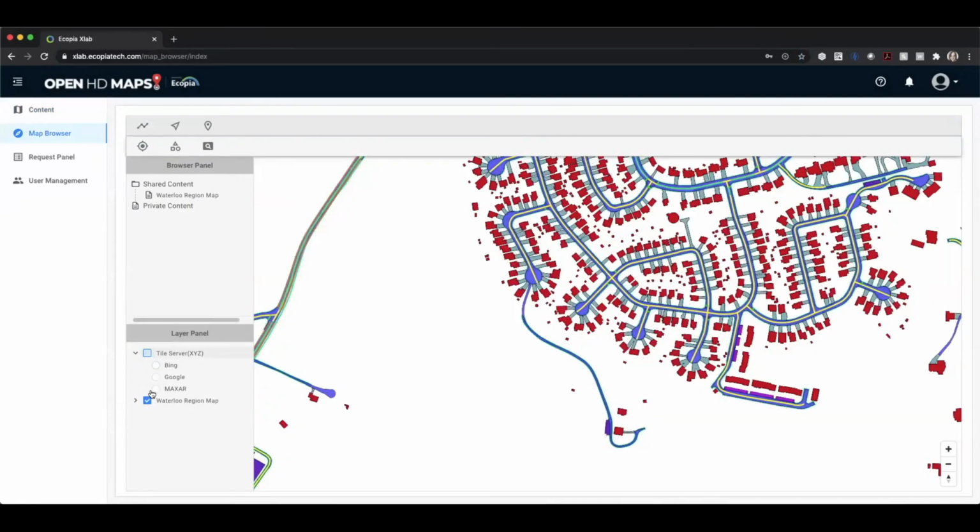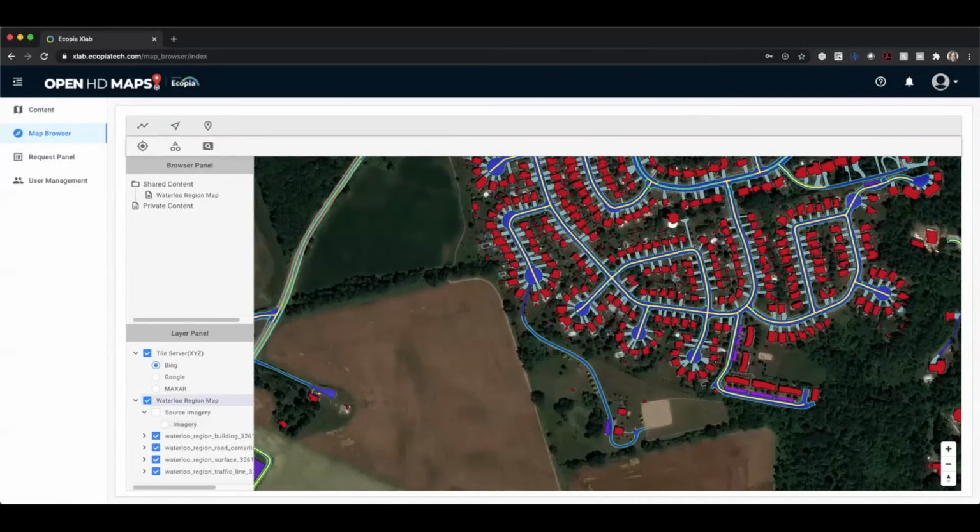I know everyone's going to ask me about accuracy, so I'll just get out in front of it. The horizontal accuracy of the layers is based on the accuracy of the source imagery. In this instance, we use 10-centimeter aerial imagery to extract the features, so all of them are extracted off of 10-centimeter aerial. The absolute horizontal accuracy is estimated to be about 30 centimeters, and the relative accuracy is estimated to be about 25 to 30 centimeters at a 95% confidence level. That means human level accuracy. That's what's widely accepted as a human level of accuracy.